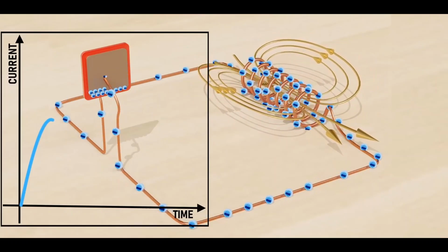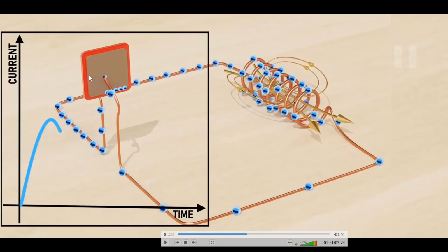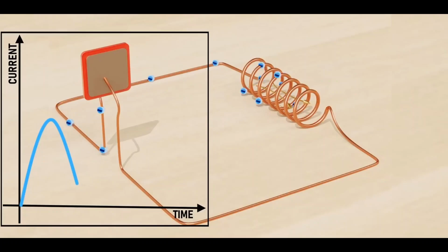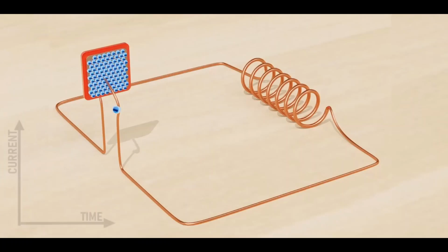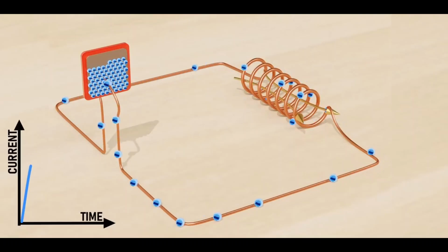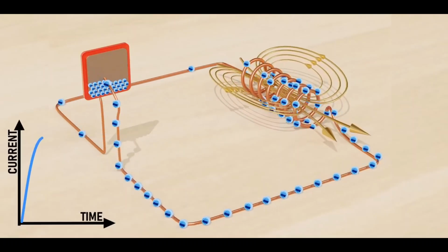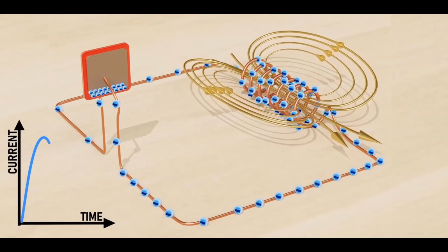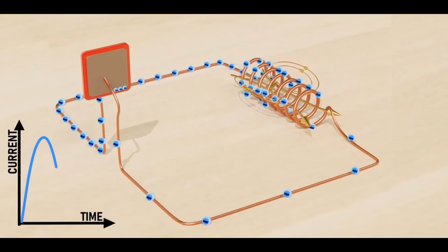In an inductor-capacitor circuit, the current flow varies. As you can see, the electrical energy is getting reduced over here, and here the magnetic energy is increasing. So when the capacitor is discharging, the inductor is charging. Variation has to be gradual, and here we can see that the current flow in the LC circuit is shaped like a sine curve. Let's look at the electron flow animation once again. The current in the circuit starts from zero and gradually achieves the maximum value. In the next quarter of a time period, the current from the capacitor starts to decrease, resulting in another change in current.